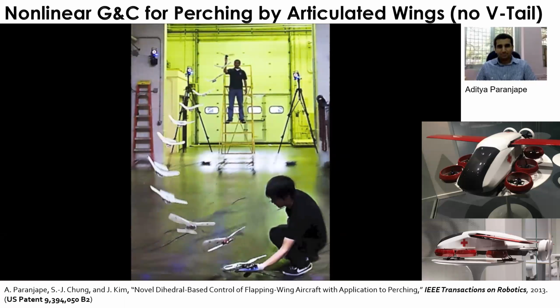So we have worked on these multiple models of this fixed wing multi-rotor, as we are seeing multiple examples here. Again, as I said, this might be useful for fast flight in a forest where you have to have a rapid turn. So you might get help from this multi-rotor system, but at the same time, in order to have endurance, a longer flight distance, you need to have a wing. So that's the difference between a purely multi-rotor system and multi-rotor combined with a wing.